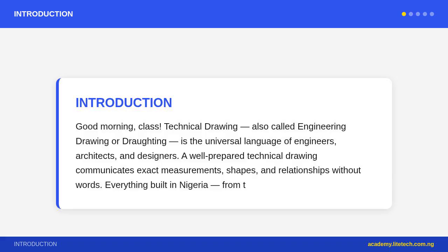Drawing board. Flat, smooth wooden or plastic surface on which drawing paper is fixed. Has a straight working edge or left side for the T-square. Standard sizes: A0, 841 by 1189 mm, A1, A2, A3, A4. WAEC uses A2. Always keep it clean and protected from scratches.